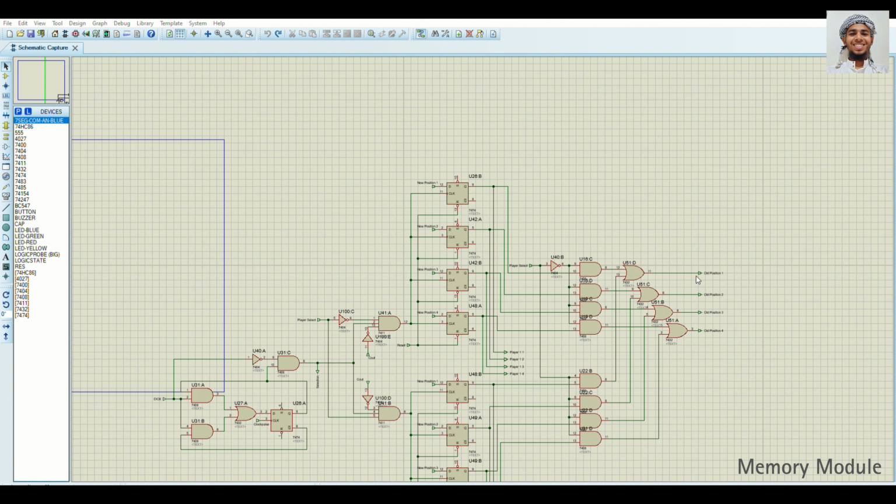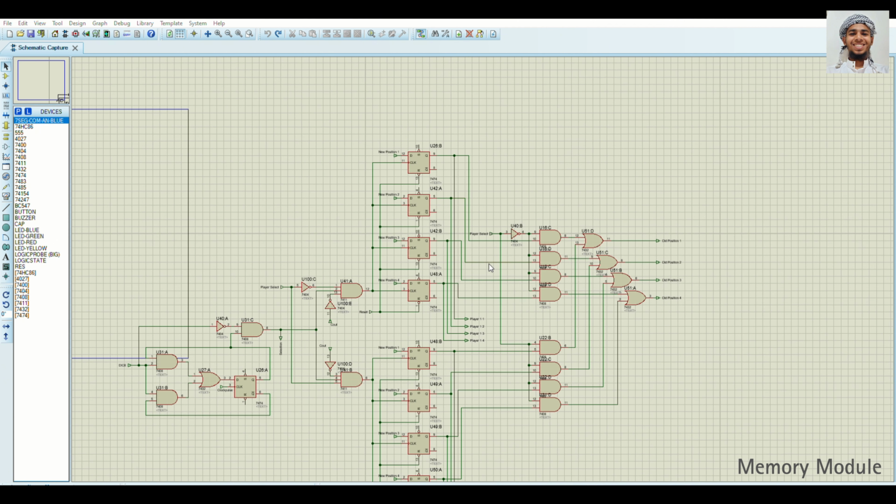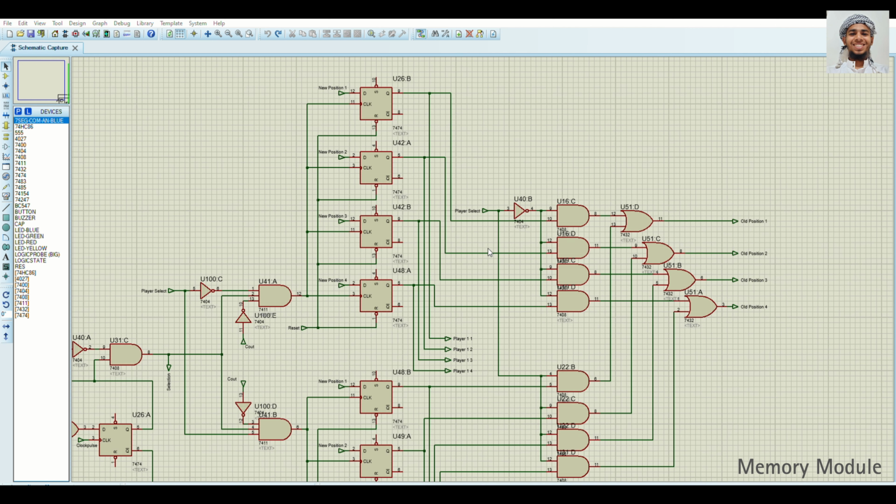These stored positions would then be used to activate the decoders and then the board module's LEDs displaying the player's locations. However, as the game is, we do not take inputs at the same time because the players don't take turns at the same time, so we do not receive the position updates at the same time. To handle this issue, a NOT gate is used alongside an AND operation on the outputs of the two sets of 4 D flip-flops.